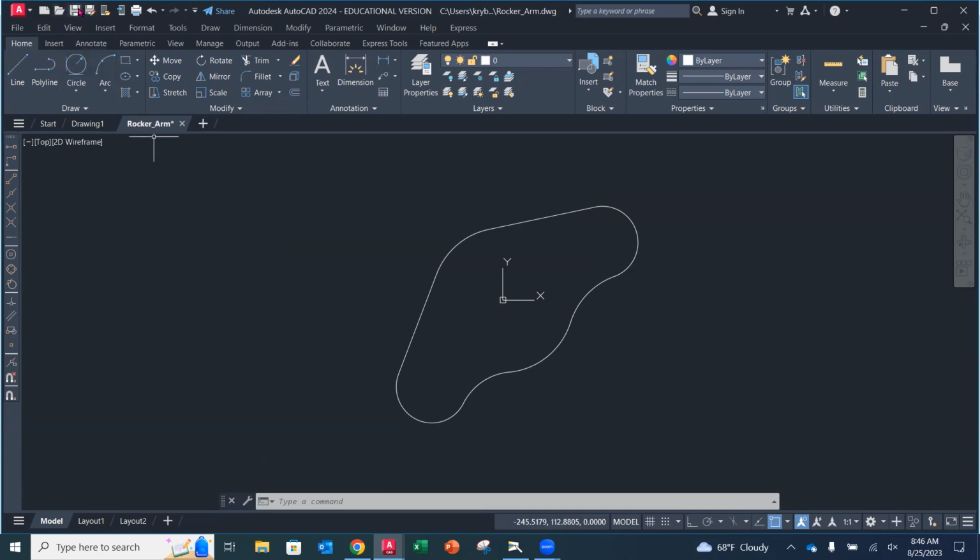What do you think? Should we do a quick save? Now that we saved, did a save as and identified, it's not a bad idea to click the save command. AutoCAD does not have an auto save. I think you can set it up in the settings, but by default, it doesn't. So we just want to save often. And when you get burnt, and you will, sometimes for whatever reason, it'll randomly stop working, and whatever you didn't save won't be there for you to come back to. So I always like to save whenever I get to a point where I don't want to redo what I just did. So kind of ask yourself that question.